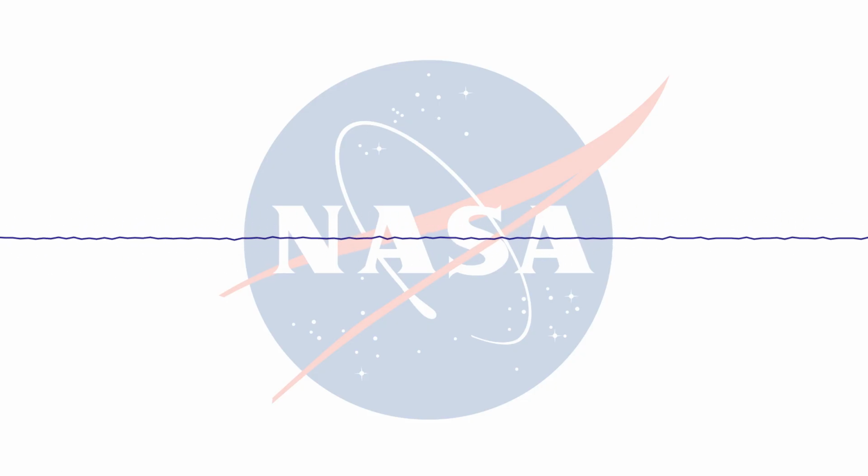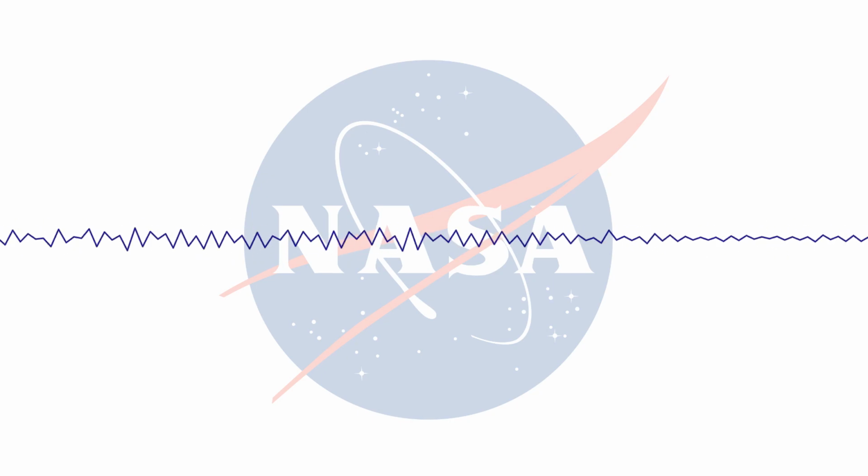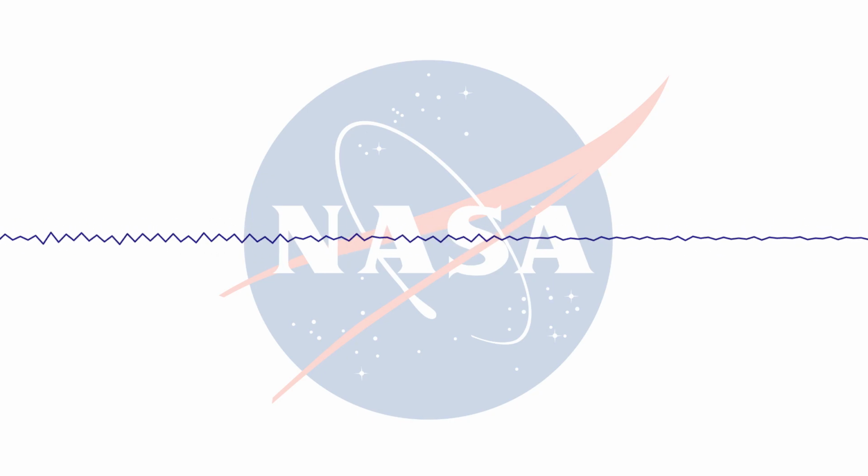Yes, quickly, the subsatellite was deployed successfully. Our spin rate was nominal, about a 5 1/8 second spin period. We want 5 plus or minus a couple. The attitude was good. According to preliminary indications from the sun sensor, we have a couple of degrees tip off from the ecliptic, which is well within the limits we needed.